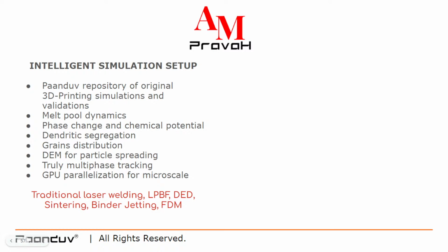It can capture melt pool dynamics, shape, size, depth of penetration. It will have phase change and chemical potential calculation capabilities, dendritic segregation, grains distribution, DEM for particle spreading. It will have truly multi-phase tracking, and when it comes down to microscale, these simulations are computationally intensive, so GPU parallelization will be included as well.